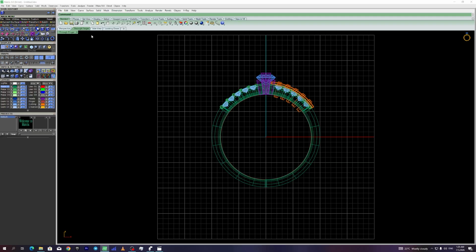It's one of the most common mistakes beginners make. They forget to check the command bar and then wonder why something isn't working. So make it a habit. Whenever you click a command, look at the command bar. It tells you exactly what to do next.